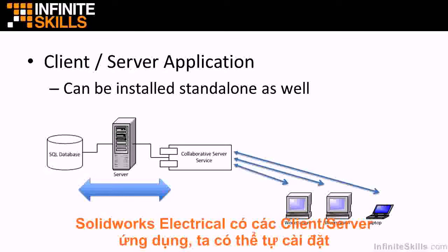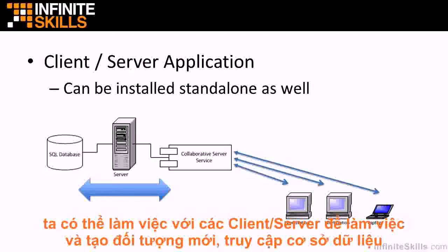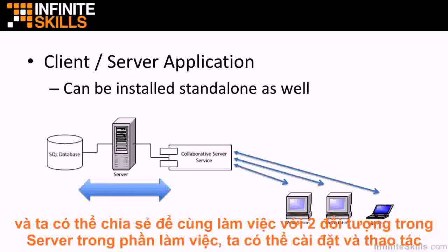SOLIDWORKS Electrical is a client-server application. Although it can be installed as a standalone application on your own personal workstation, the most common way of using it is to install it on a server with an SQL database installed on it. The collaborative server service is installed by SOLIDWORKS Electrical. This will allow workstations to connect to the server to perform actions like creating new projects, accessing the database, and communicating with other users simultaneously while working on the same project.